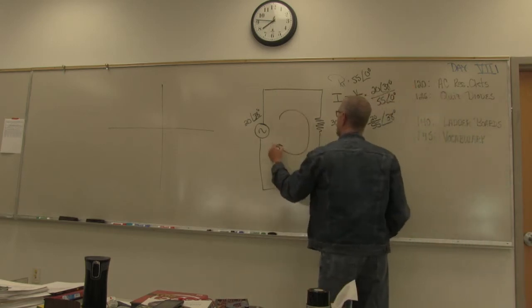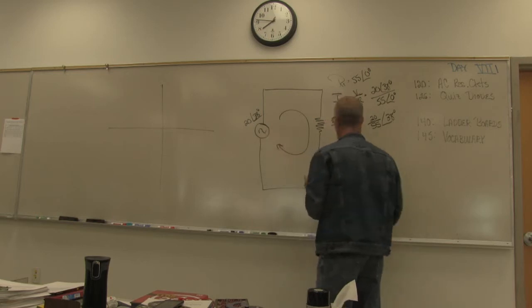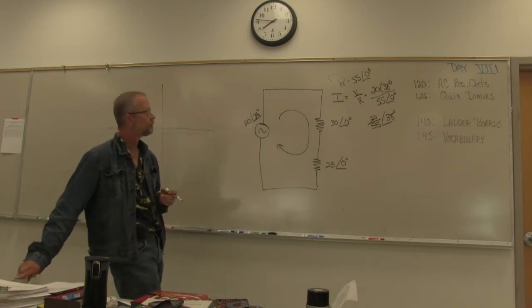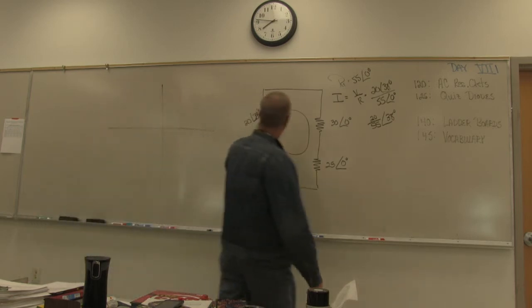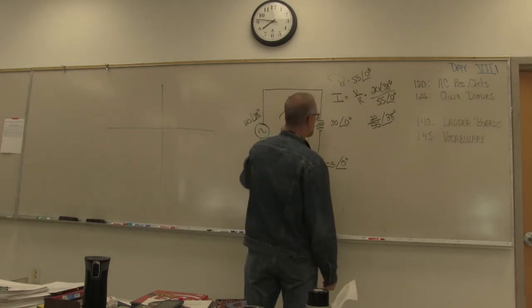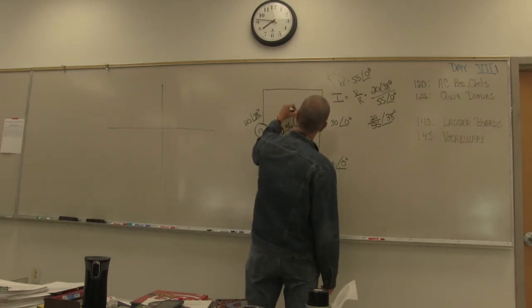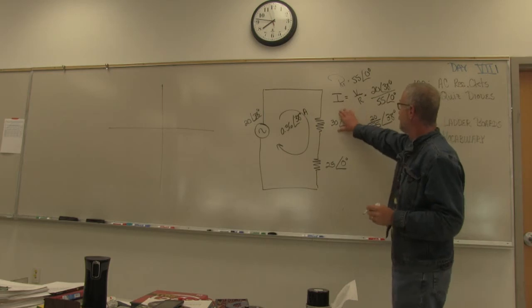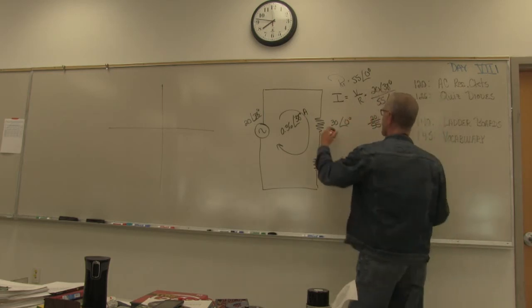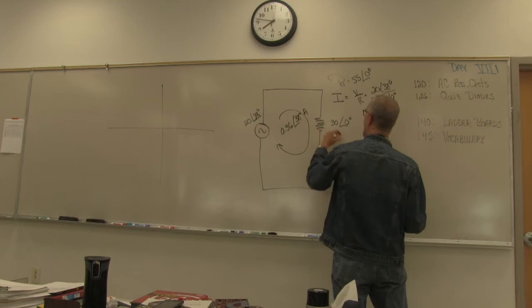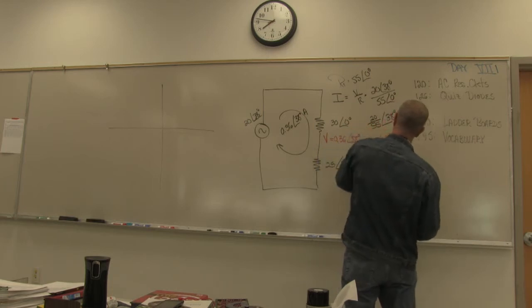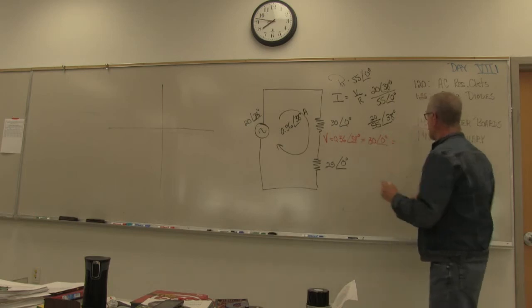So that means our current will be whatever that is. What's 20 55ths? Almost a third. 0.36. 0.36 at an angle of 38 degrees, amperes. Okay? Then we can take these and determine what our voltages are. V is equal to I, which is 0.36 at an angle of 38 degrees, times 30 at an angle of 0 degrees. 38 plus 0 gives us 38 degrees.